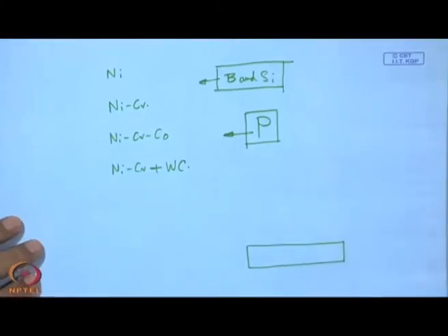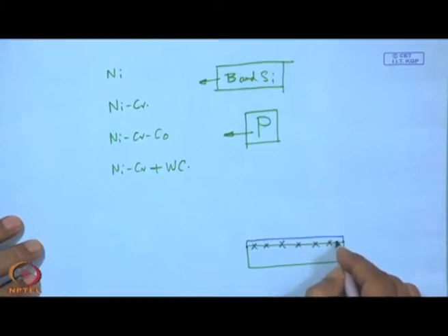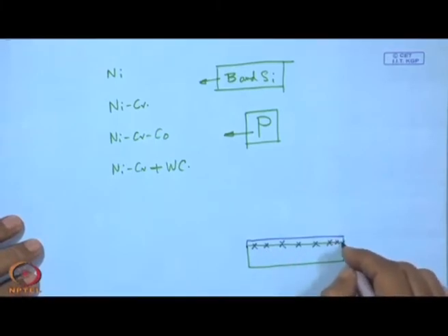we deposit the material, but it is not exactly the case that chemical or metallurgical bond formation takes place then and there. No, it is not the case. It is just added to that, and it may be a little bit metallurgically bonded, but mostly it is mechanically interlocked, which we are going to discuss. So, this is just the formation, and then if we like to have a metallurgical bond, we must melt it.